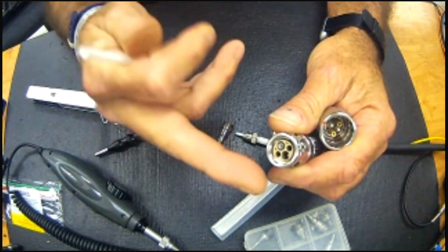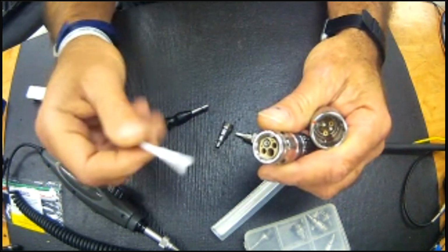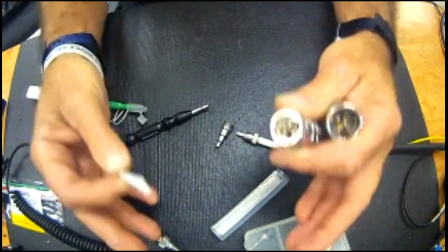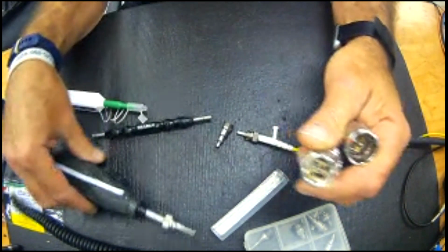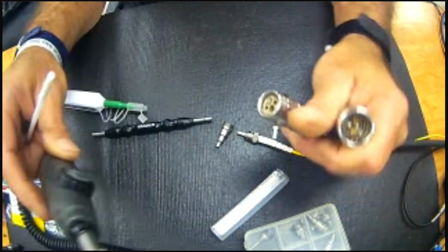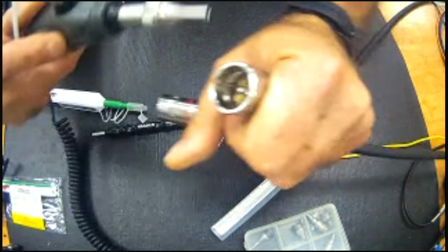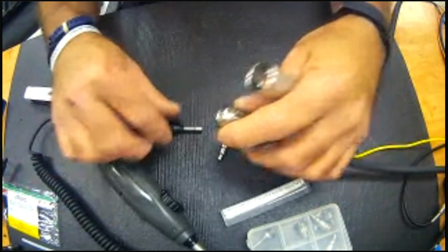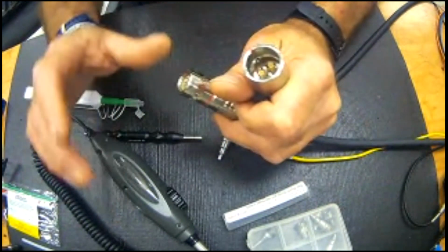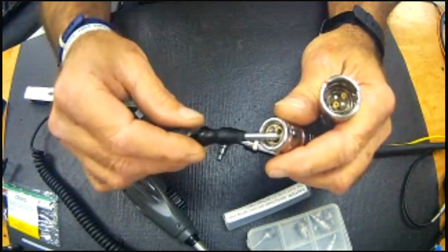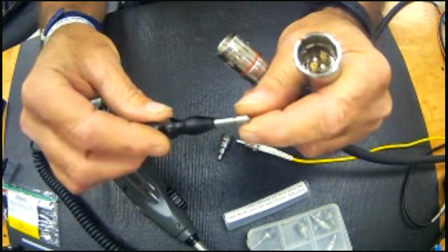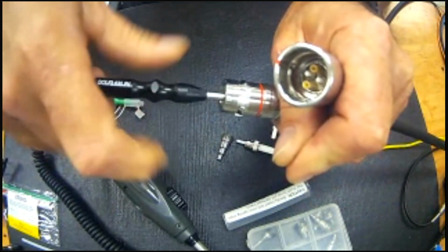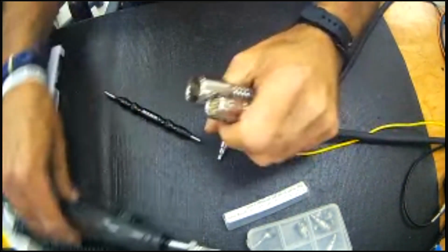If you have dirt, you'll actually have to use a little bit of alcohol and go wet, dry, wet, dry, wet, dry, several cleans. Your cameras need a lot of cleaning, I can assure you. If you owned one of these and you visually inspected the receptacle that's on your camera, you would be amazed at the amount of garbage, the amount of attenuation that you're experiencing just on your camera ports. So after you've cleaned it, to reinsert it, you simply thread it back onto the tool. You reach in, press till it snaps, unthread the tool, voila, you're done.